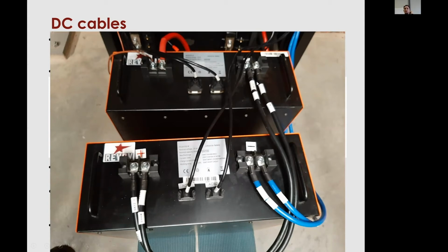And then you have 2 25 millimeter cables swinging around as the black ones and connecting to the negative and positive. And then from the back end, you got the negative coming out, going up to the BMS, and that's also 2 cables. These cable lengths have been matched to each other.